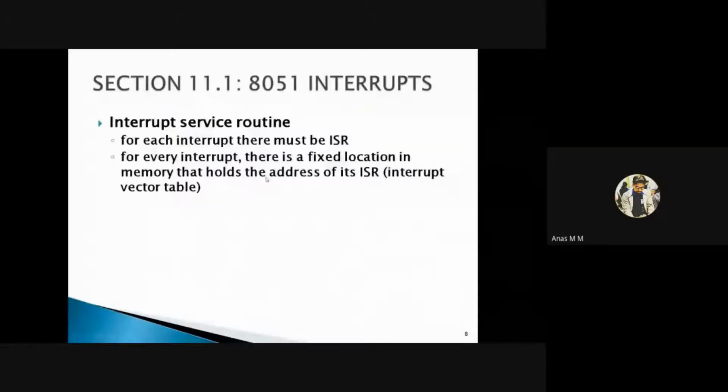And ISR, interrupt service routine. For every interrupt, there is a fixed location in the memory that holds the address of the interrupt service routine. So usually in our system, the 8051 microcontroller, there is the ROM memory. In that ROM memory, we allocate certain memory locations for each interrupt. So that is the interrupt service routine.